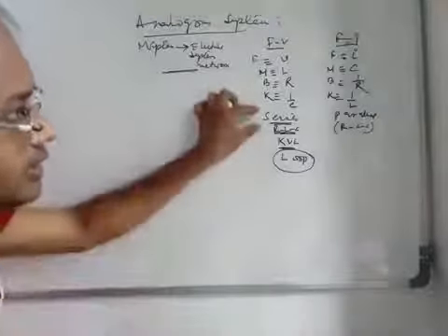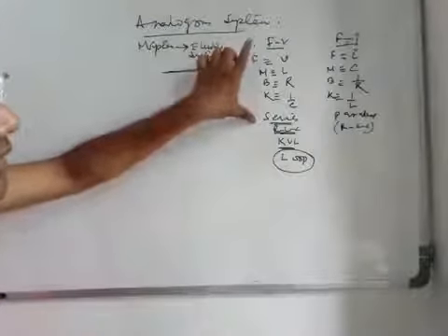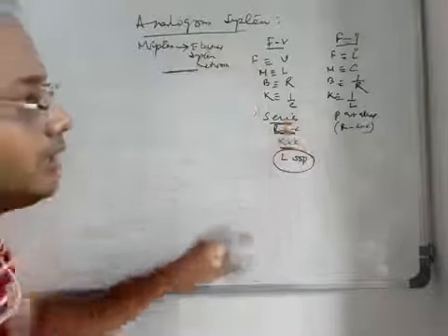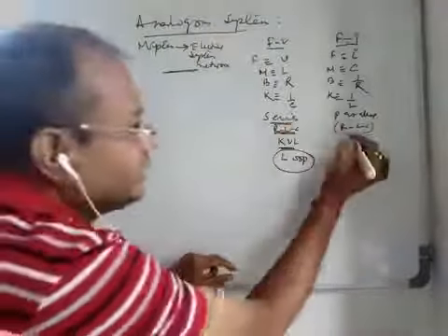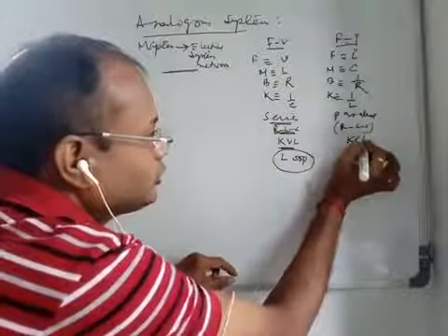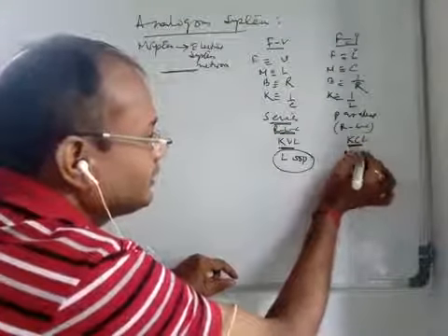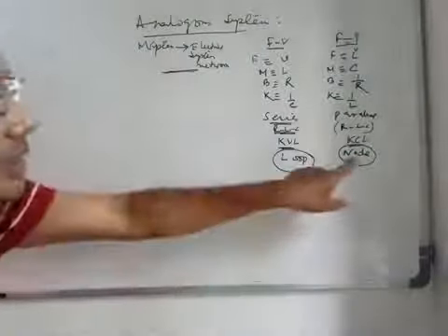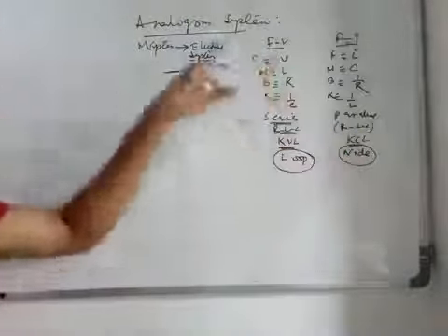This series RLC circuit in the electrical system corresponds to a force voltage analogy. And when we consider a parallel RLC circuit, we use the tool KCL, that means the concept of node. So here current is the forcing function, and here voltage is the forcing function.